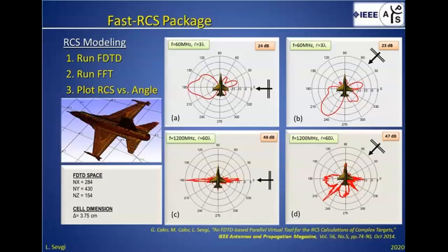And for each one, the first important thing for the RCS engineer is that whatever the frequency or angle of illumination are, it doesn't matter. The strongest contribution, the RCS contribution, is the forward scattered component. You see, the forward scatter is always dominant in RCS engineering. Next slide, please.